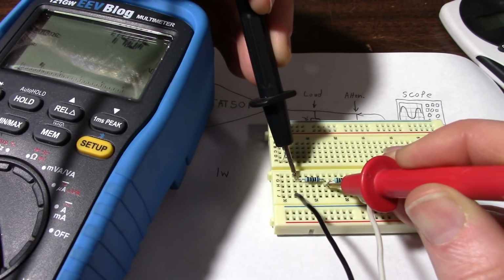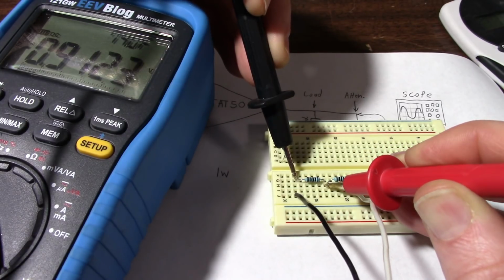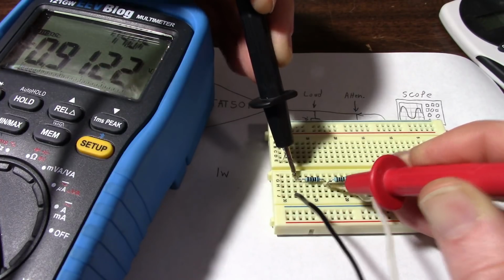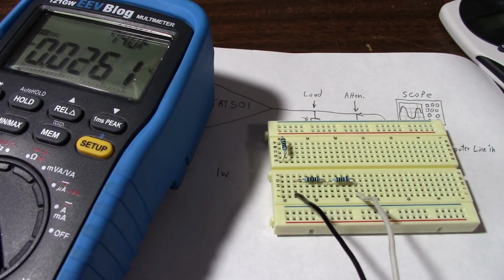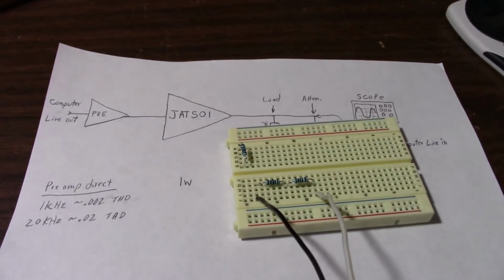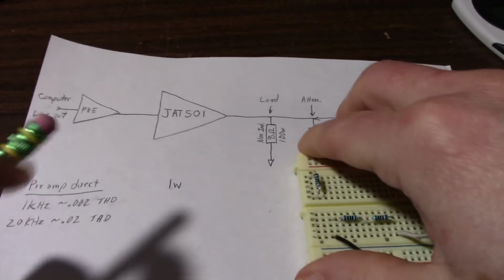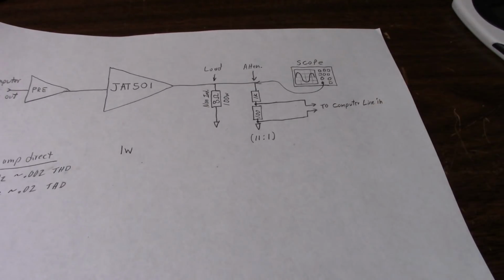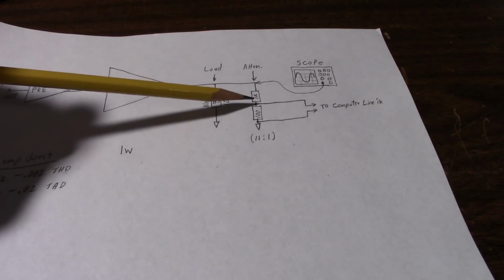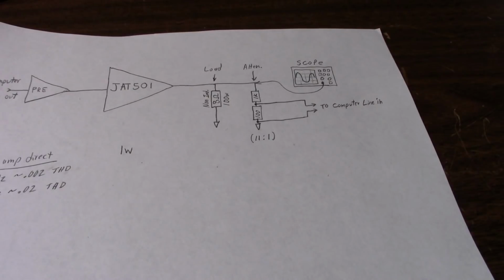So at the center point, we're getting 912 millivolts. So if we actually do the calculation there, it's 1K ohms plus 100, so it's actually 1100 ohms. So 10 volts divided by 1100 gives us 0.00090909 amps.